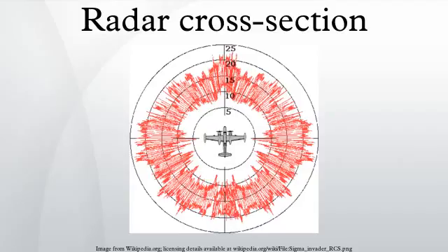Shape, directivity and orientation. The surfaces of the F-117A are designed to be flat and very angled. This has the effect that radar will be incident at a large angle that will then bounce off at a similarly high reflected angle. It is forward scattered. The edges are sharp to prevent there being rounded surfaces. Rounded surfaces will often have some portion of the surface normal to the radar source.